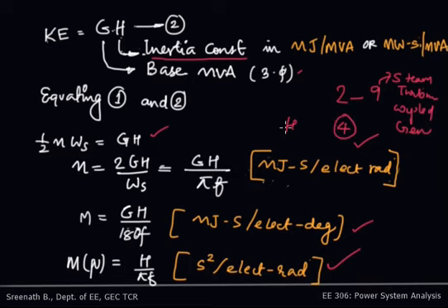Okay, for hydro. Now the importance is that once you have a value of 9, that simply means that your system is having a larger inertia available, or larger capacity to store energy in the rotating mass. So that stored energy is being converted into electrical energy.